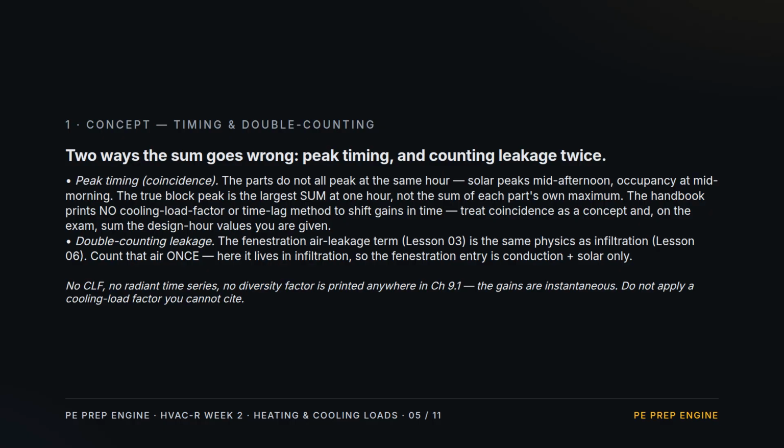Second, double counting. Window and door leakage is the same air as infiltration. Count it once. We put it in infiltration, so the fenestration entry is conduction and solar only.